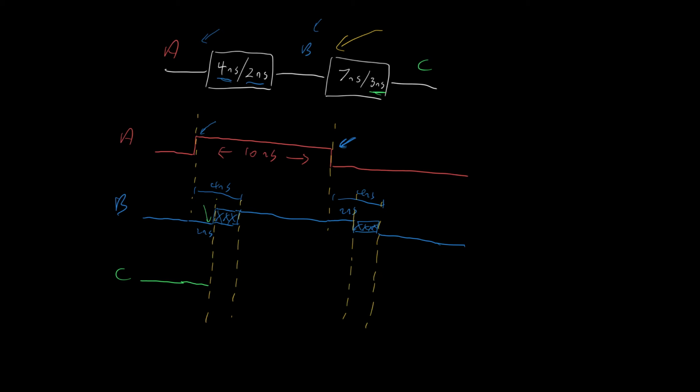The width of these two dotted yellow lines is 2 nanoseconds, so 3 nanoseconds brings us to this point here. So from here to here, this interval is 3 nanoseconds. After the contamination timer has elapsed, we enter a period of don't know, don't care.